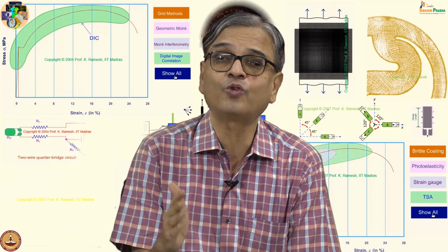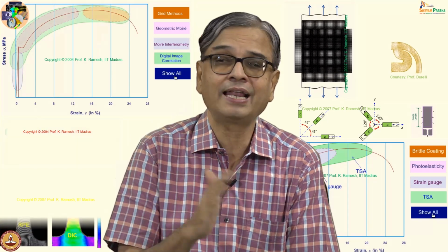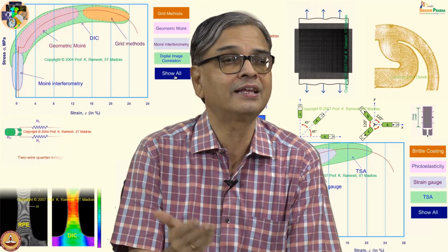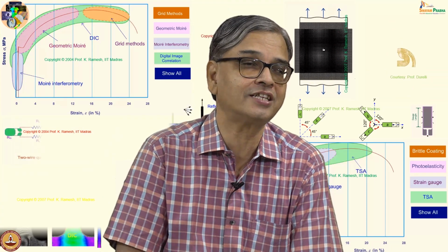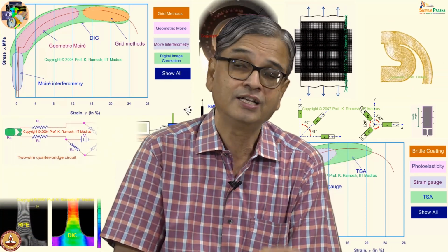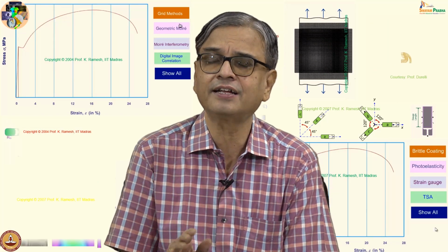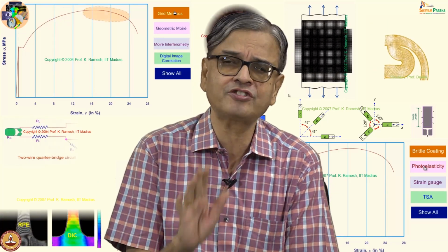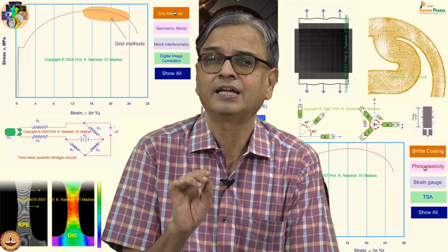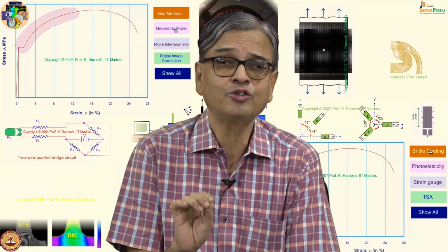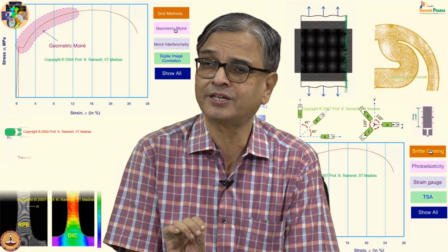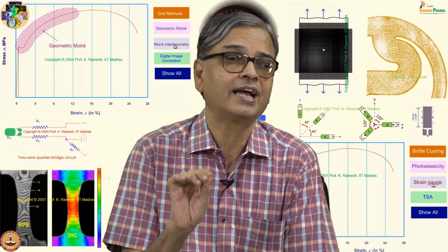Don't simply use whatever strain gauge is available at the 11th hour, try to make the measurement, and finally blame the technique that the strain gauge technique is not giving you correct results. It's a very sophisticated technique. You have to be sensitive from the first stage of the experiment, handle the technology, listen to all the manufacturer's recommendations, paste the strain gauge and make the measurement.